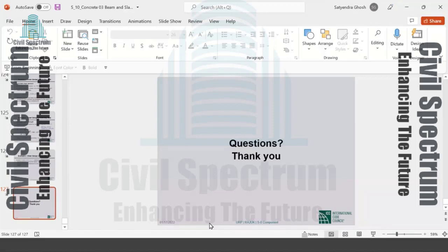It is the bending in the short direction that counts. Then we call it a one-way slab. That's all there is to it. There is no one-way slab that is not beam supported; it cannot exist. All slabs without beams are two-way slabs. If you have beam supported slabs, whether it's one way or two way will depend on the dimensions of the slab panel. That is probably the best way to say it.